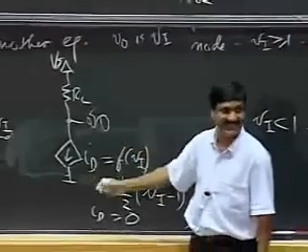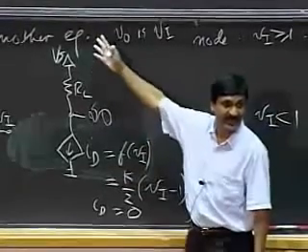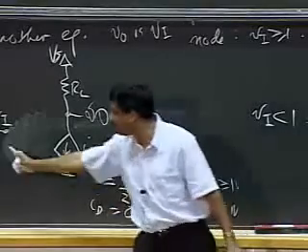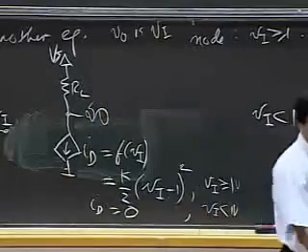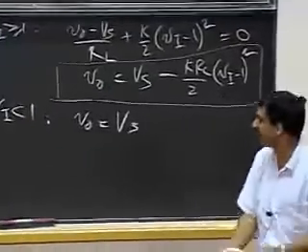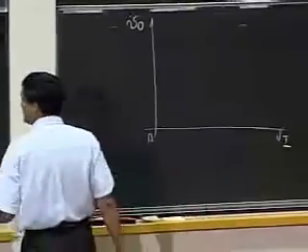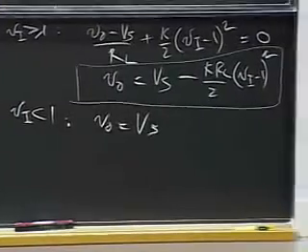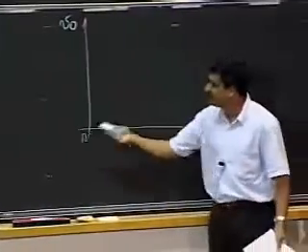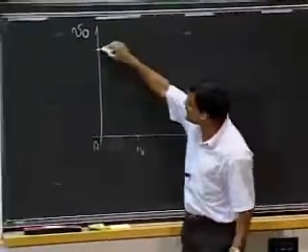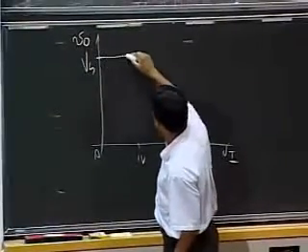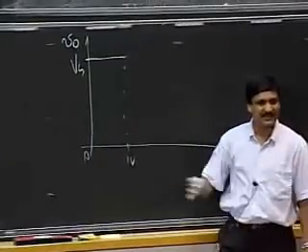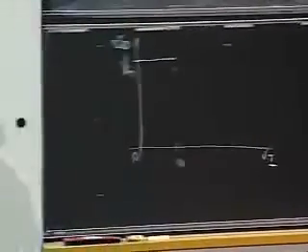This has got nothing. It's got a RL resistor connected to a supply and a dependent current source. I can apply some voltage Vi at the input. Very, very simple circuit. So as long as Vi is less than 1, the output stays at Vs. Okay, that makes intuitive sense, right?